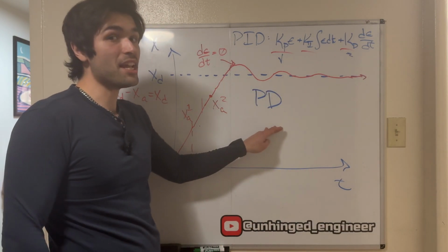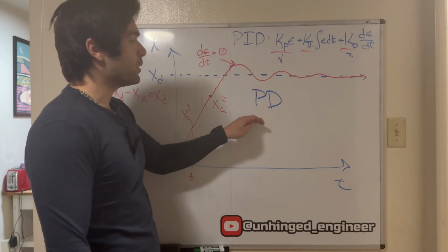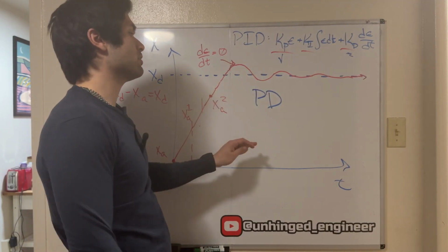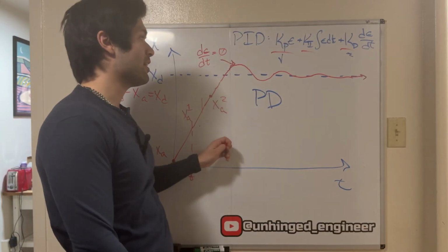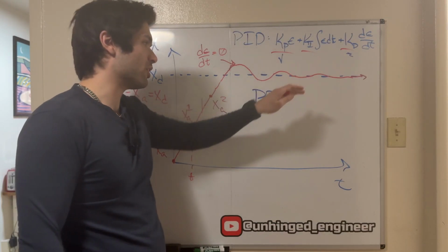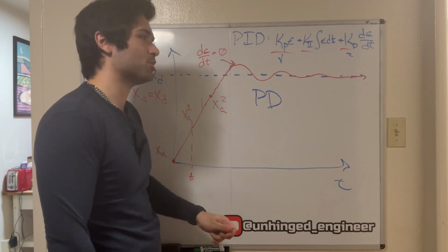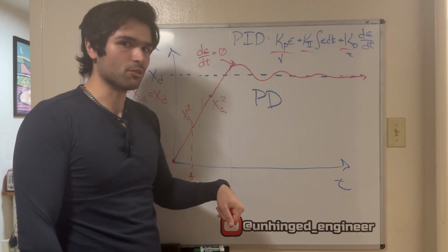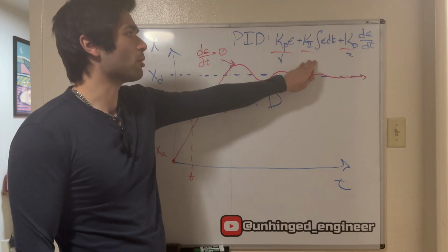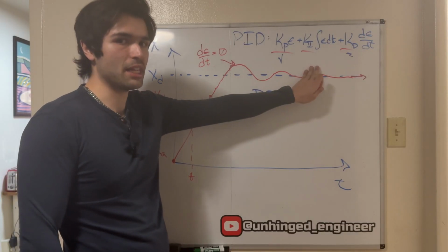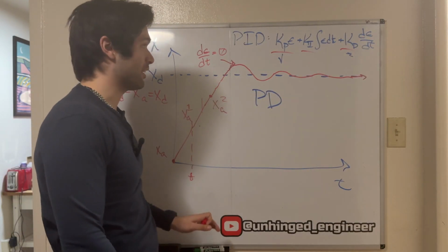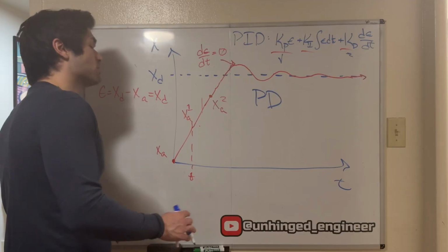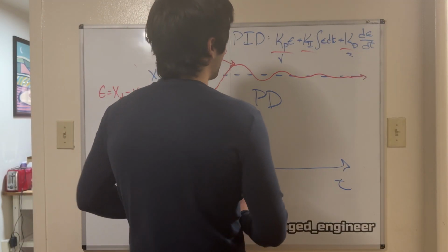And a lot of times it actually is, but sometimes we need this integral term. It does complicate things with how you store your integral and integral windup in certain applications, but we're not going to talk about that in the course of the video. So the integral term is actually kind of the last one we add, usually for the most part, right? Because if we don't need it, we avoid it.